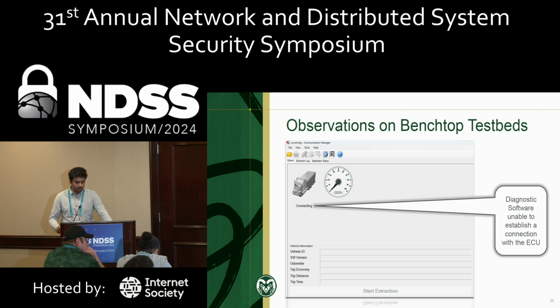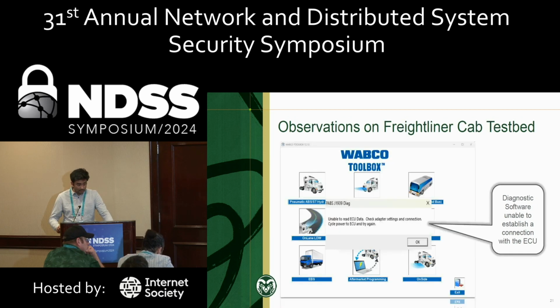And this can be impactful because if an attacker is present during a diagnostic session, the tester may not be able to establish a valid session and perform diagnostics. The same was observed on the Freightliner test bench as well, and as you can see from the screenshot, it clearly says unable to read ECU data, check adapter settings. Adapter settings were correct, however, the diagnostic software could never establish a connection.